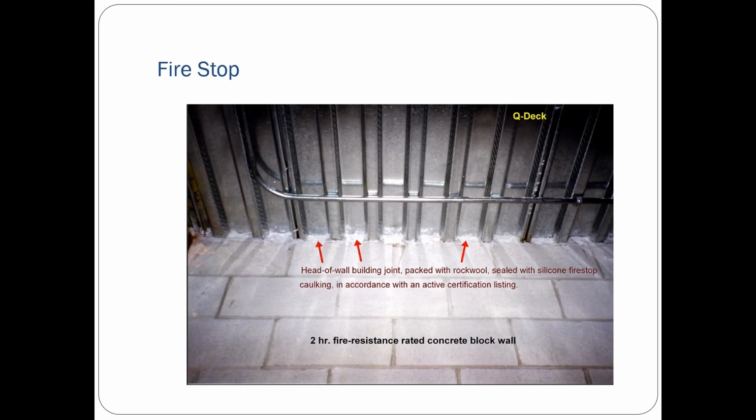Beyond electrical terminology and print terminology, I also need to be aware of technical terms that other people use within the trade. Things like fire stop, which is the fire barrier between two areas of the same building. And that's important to us because as we run conduit through different walls, some of those walls are fire partitions and they need to maintain that fire stop, which means we need to re-caulk our holes to make sure that we don't have any fire penetration from one area to the other.